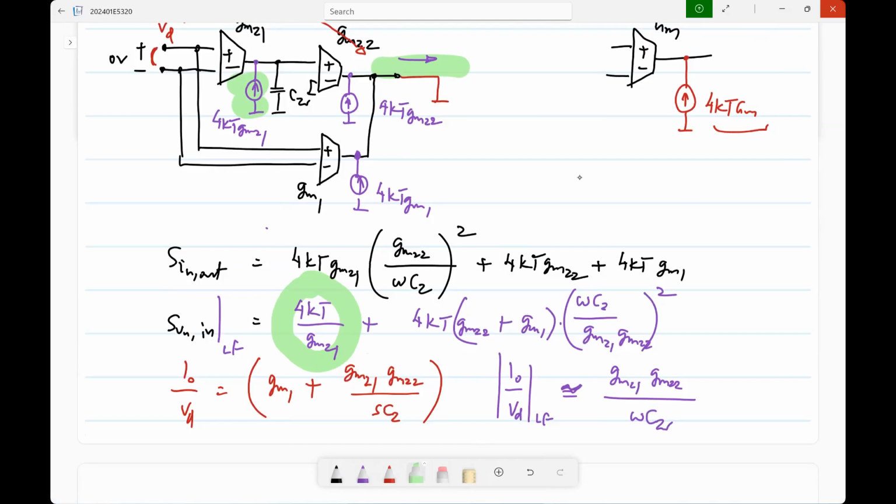Basically, I think I just chose it so that the lower the VDsat for a given current, you have the larger transistor size. And the first stage current is likely to be smaller anyway. So, if I gave 250, probably you'll find that the sizes are even smaller than the minimum width or something. So, with that, I think I just somewhat arbitrarily chose some voltages.